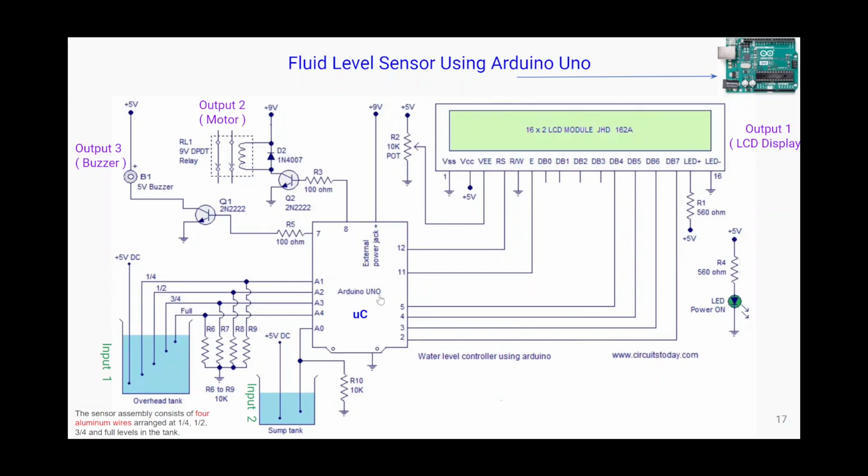So these are Arduino Uno analog inputs connected with the analog to digital converter. The program which we have written for the microcontroller will be continuously monitoring these ports for any digital change. The analog to digital converter inside will be providing the data on these respective ports. Whenever there is some high digital value on the respective port, it means the water level is at that particular level.